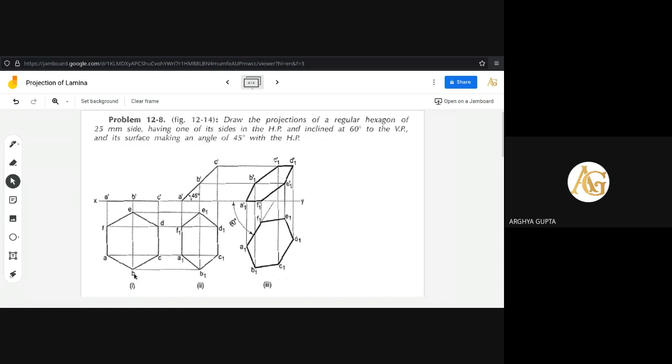So this is the first step. And on the second step, you have to draw the same length line, that is A dash to C dash line, at an angle of 45 degree, and taking the measurement of A dash to B dash by means of a divider or pencil compass, mark that B dash point here. Okay. So now through all the 3 points, draw perpendicular lines, projection lines, and through all the